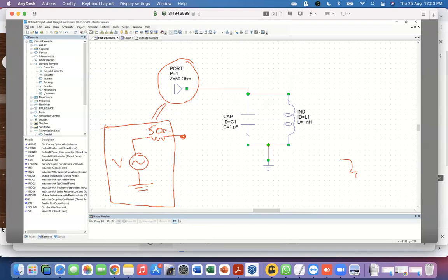And this can also be drawn in a current source model. I think some of you are getting nightmares about the Thevenin and Norton equivalence, but you could also draw it as a current source with the value I equal to V over 50, because the previous one was 50 ohms, and this is 50 ohms. And this box is the same as this one. So that's what putting a port here really means. Either of these two are equivalent, which means I can excite.